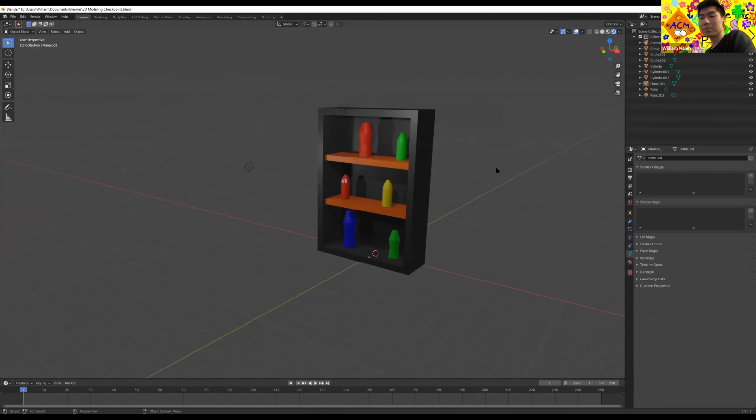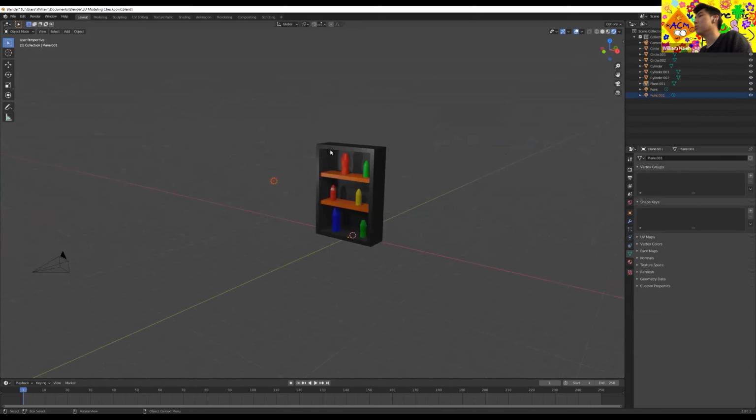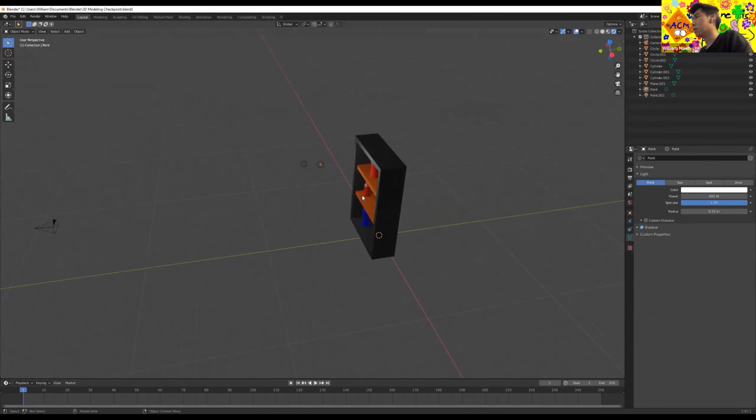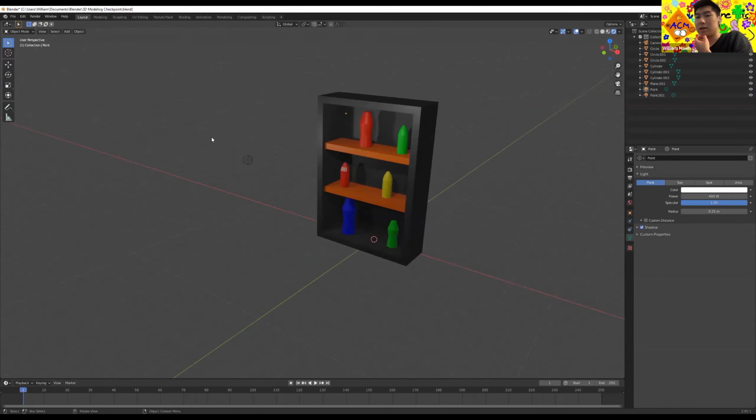Yeah, for sure. Cannot see the shadow render. That might be because you don't have any lights. The same way you make the camera and every other object, you would Shift A, add a light. When you add it, it's very not bright.